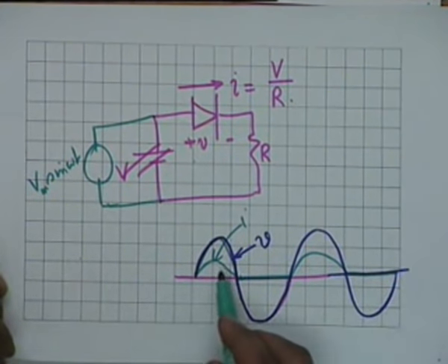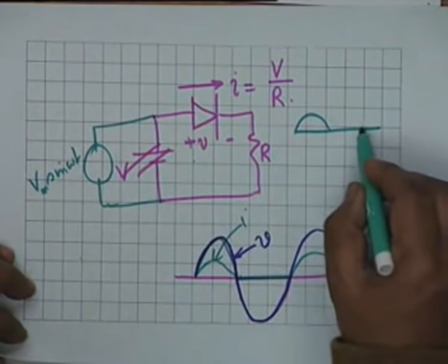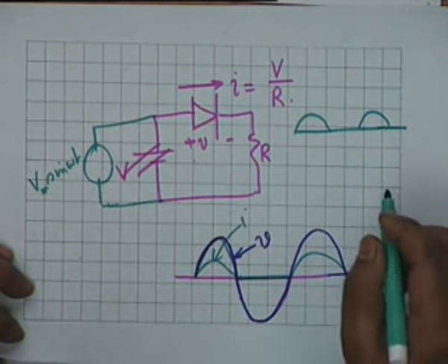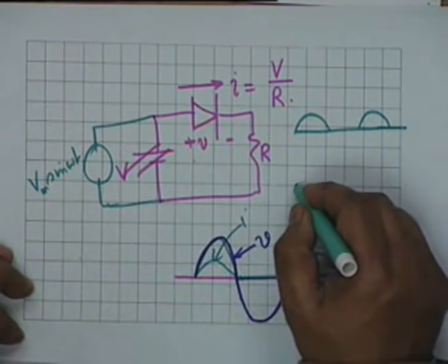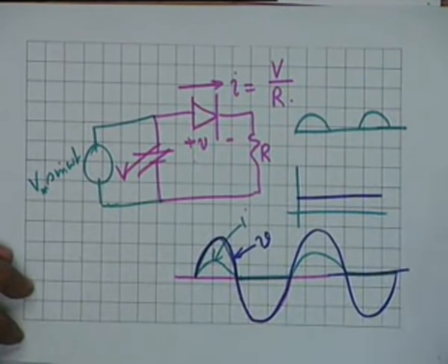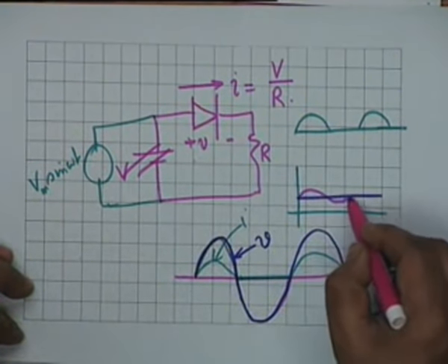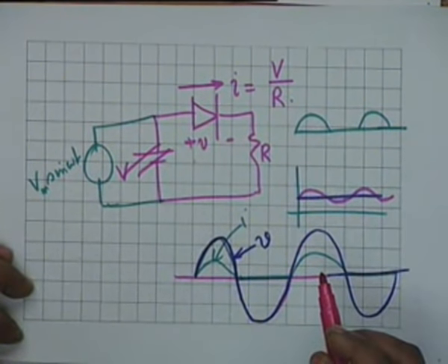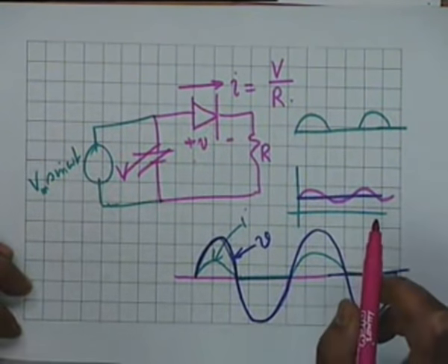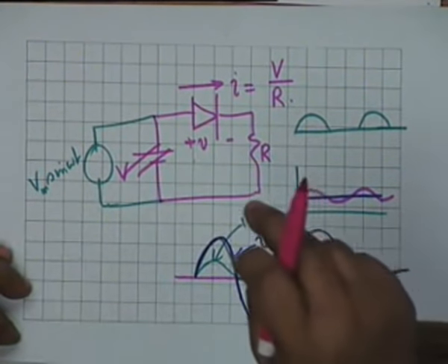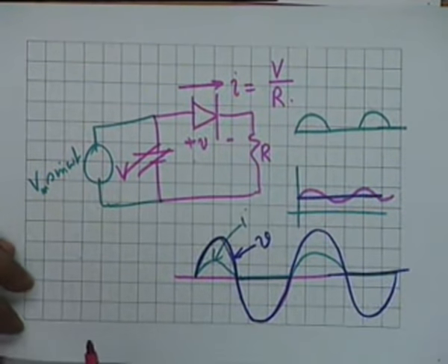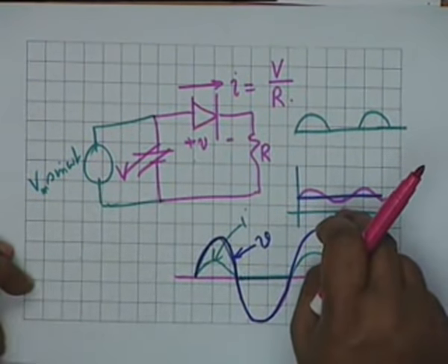All right. So, this voltage, let us now consider the voltage, only half cycles. This voltage can be thought of as an average voltage, like this, on which is superimposed an alternating voltage like this. We can think of it like this. And usually, if you want to convert AC to DC, what we want is this violet line. We don't want this AC superimposed on the violet line.